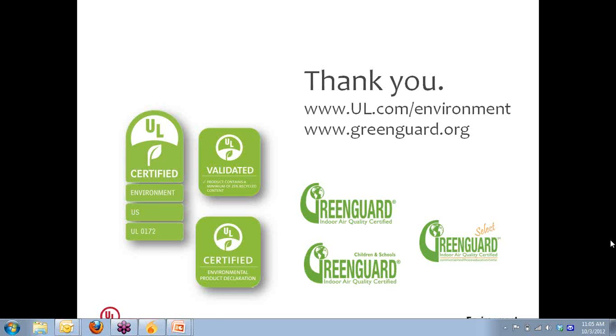Anything else? Good questions. My third-party IAQ report measures carbon monoxide and CO2 in parts per million. Yes, parts per billion is another way that chemical emissions are measured. Micrograms per cubic meter, parts per million, parts per billion. You'll see that listed sometimes both ways. Either way is fine. The conversion from micrograms to parts per million is this very long formula which you really are not interested in. So go with either one. Either one is acceptable.